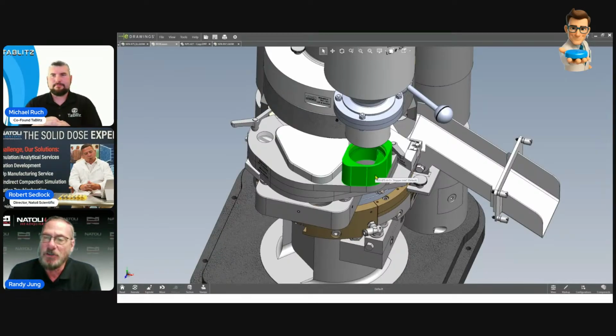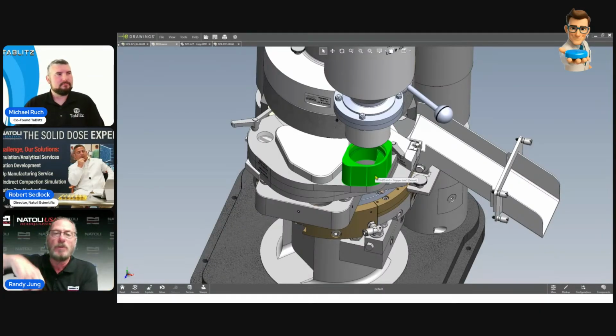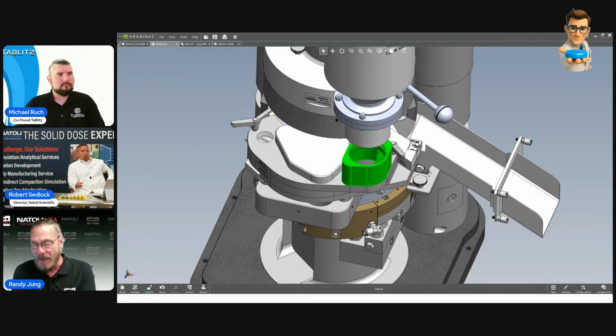Yeah, Mike. Just so you know, because we work with a lot of different companies, this is one style of machine. You can see this inlet is different than the one I showed you. That inlet that we 3D printed was on a machine that ran a standard hopper. It didn't really require it. Would the valve have helped? Not really, because I still had an opening that's this big. But I did want to bring up that you don't have to have this complex fill system above it always to remediate issues. There's other ways to do it.